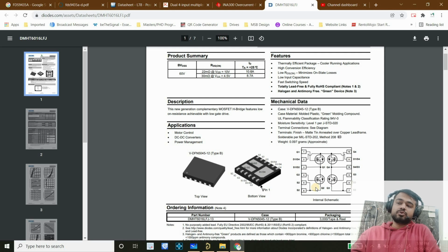I wanted to rotate a motor, let's suppose clockwise, okay? And whenever you want to rotate a motor, there will be 2 MOSFETs connected in series. That means RDS on of 2 MOSFETs will be in series. That will be the total voltage drop of this chip for clockwise and for counterclockwise as well. So here we'll see, this is the configuration that we are using.